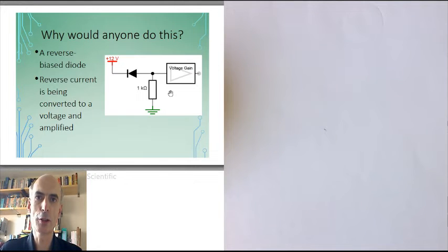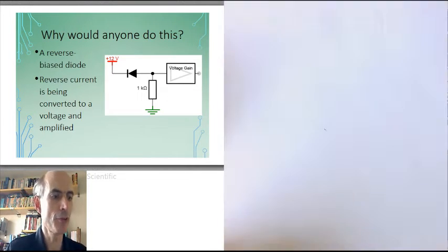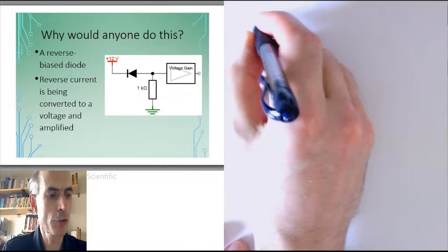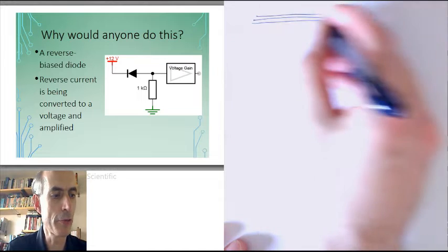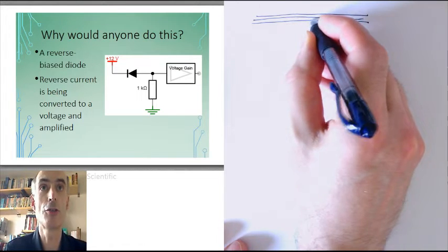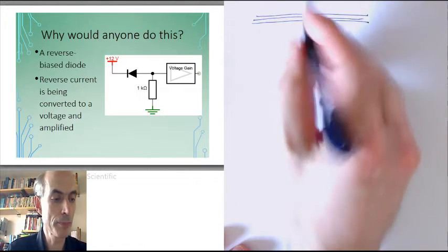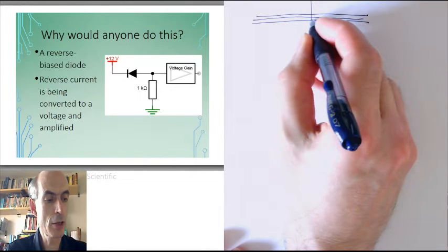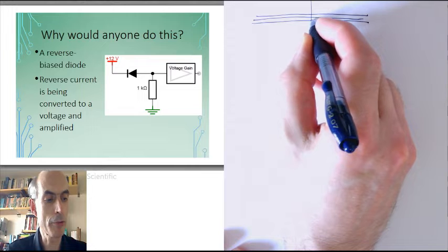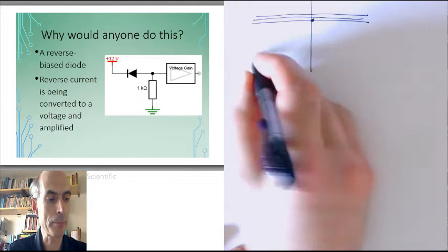First reason goes back to considering why this saturation current exists at all. Now, if you remember, the saturation current occurs because we have not a zero population of electrons in the conduction band near the junction, but because of the Fermi Dirac distribution, there is a small number of mobile electrons up there.